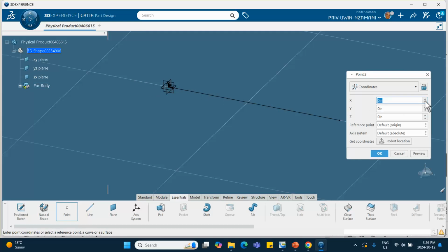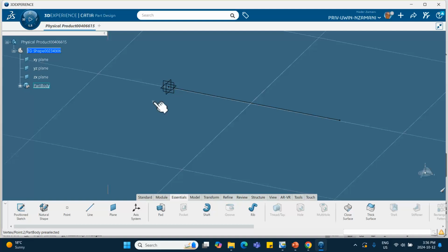So let me make this maybe just for visual purposes, so I can see it, 2 inches in the x direction, right there. There's a point here. If I don't make a point for the specified orientation, when I try to apply the beam section, it's not going to take it. You're going to get an exclamation mark here. As a matter of fact, I created this point, but we'll worry about it later on.